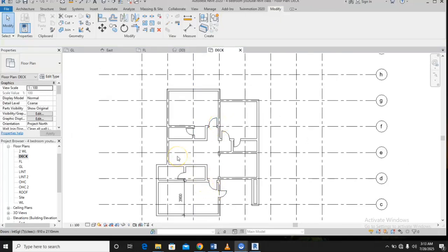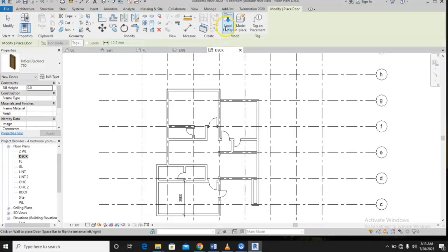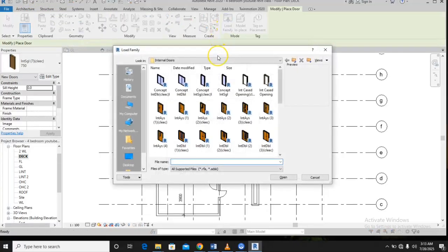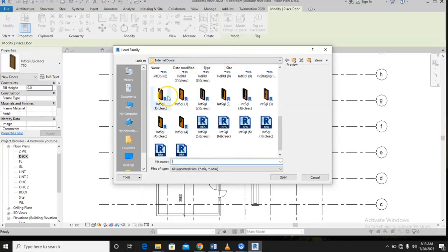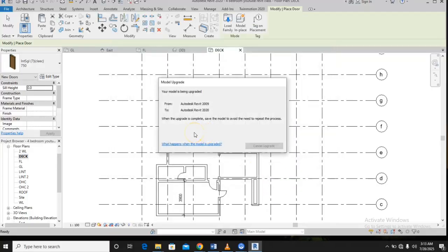Yes, so it's okay. So I've increased it, but in our floor plan now we are having that particular wall. So from here now we're having this place. I want to put a sliding door. So I'll come and click on architecture, go to door, go back to load. Let's go back. Or you can still go back to here. These are internal release door, so you can use this one, any one you want. Let me just use the first one. These are sliding doors.